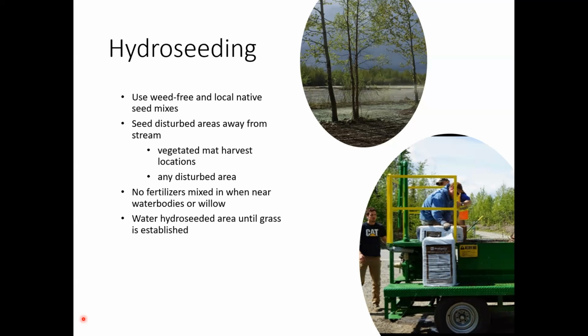As mentioned with all of the other techniques, post-application care is critical, especially in hot or dry sites. Note that hydroseeding is not recommended over newly planted trees, willow stakes, trenched willows, or any potted plantings as well. And fertilizer is not allowable when hydroseeding near water bodies. And also with this technique, we have had issues with invasive species being present in purchased seed mixes. So it's imperative to take special care to ensure that your seed mix is clean before it is used at your project site.